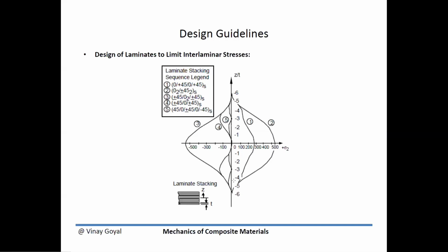One thing you can do is perform a highly refined finite element analysis, not classical plate theory, but something more advanced than that, and look at the mesh and make sure you have a good, fine mesh density to study which stacking sequence may be the best for you. So again, very important consideration for composites.